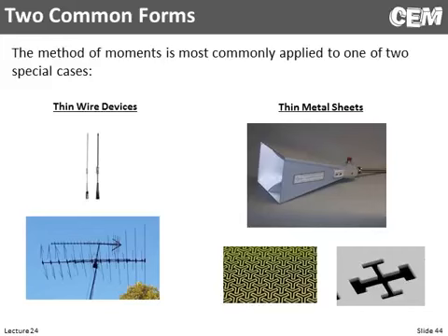That's very cool. And the math really simplifies down, particularly when we're modeling metallic structures. So if I see an all-metal structure, thin wire antenna, or something made out of metal sheets, I'm immediately thinking in my head, this is going to be great for method of moments.